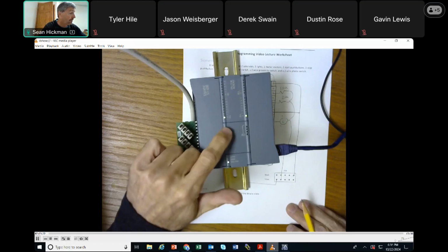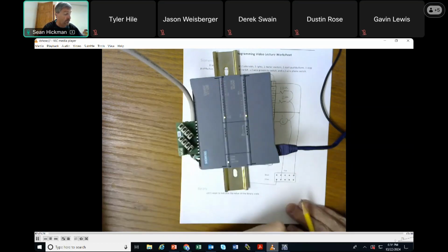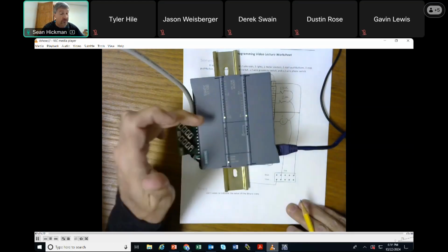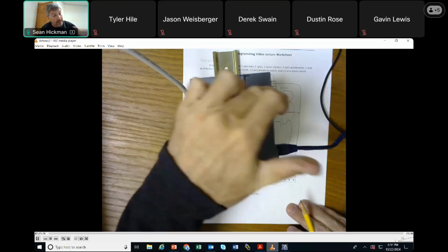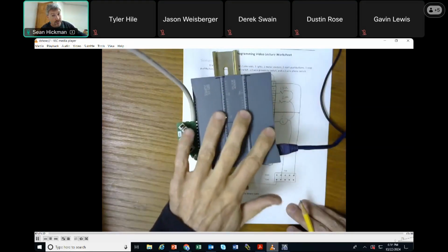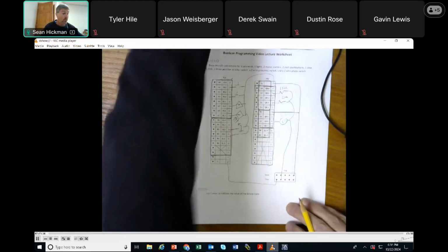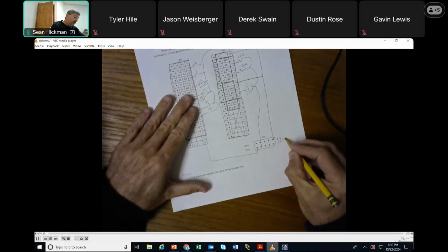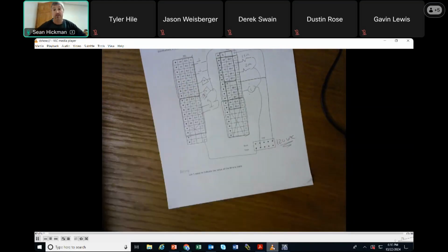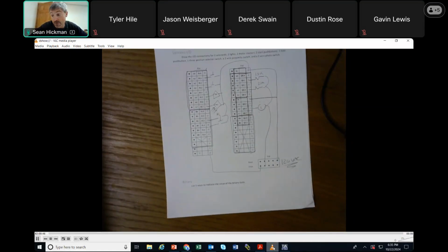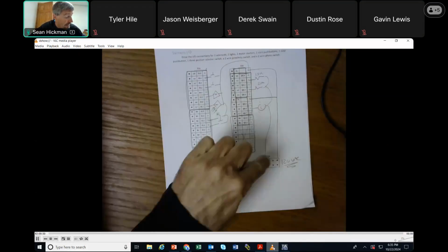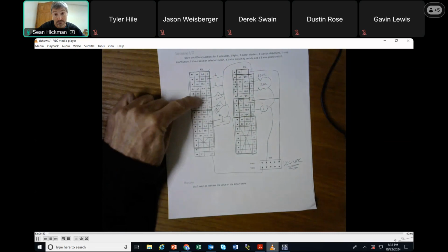Now here's another thing. These are what we have here. It's AC-DC relay. So this is powered by AC. It has DC inputs and relay outputs. That's the way this unit is. Well, our issue is we are using a training board that we've repurposed. And we already know on our training board, because we have all these 131 components, that we use AC. So you cannot run AC into this input module because it's a DC input module.